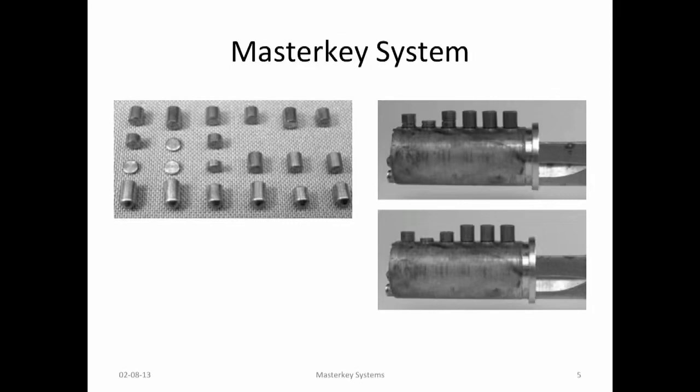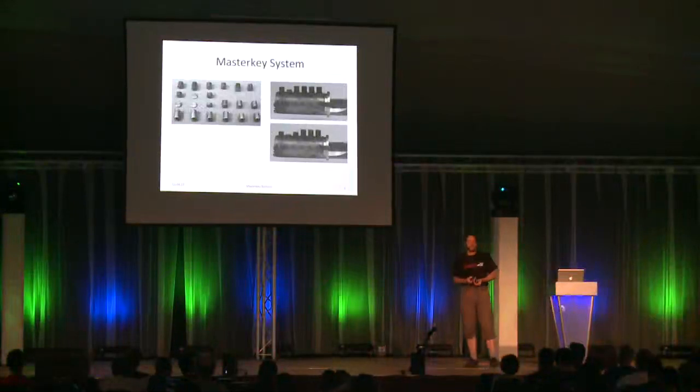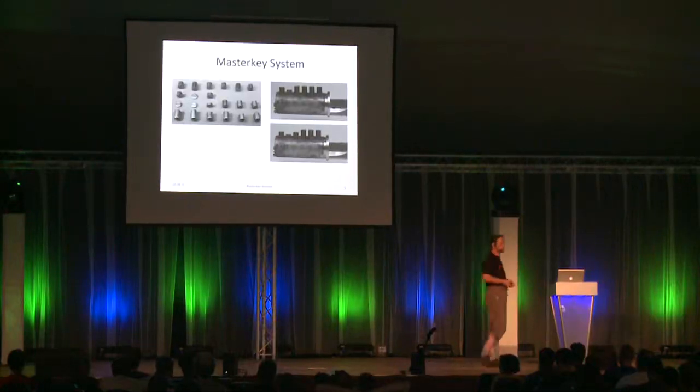In the traditional master key system, you have to make different keys that open the lock. The second thing, you have what we call master pins here, so that many keys can open this lock. Different keys push the pins to different heights, and you also have a shear line at each position. So keys with different bitting can open this lock. This is the simplest master key system. It's just one keyway, and every key fits the lock.